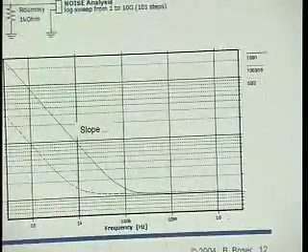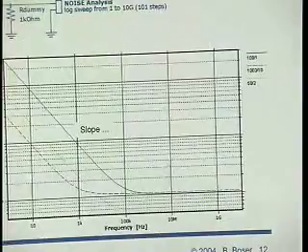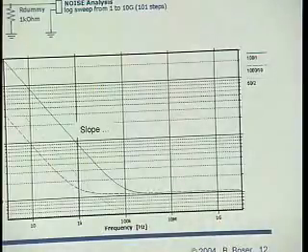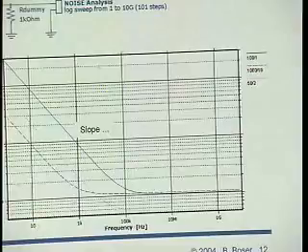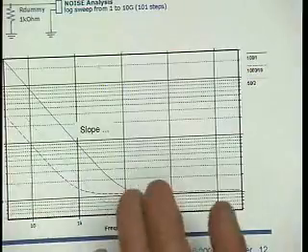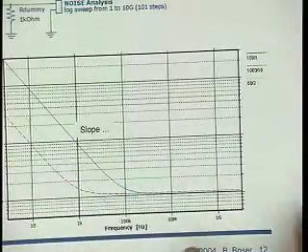The physical explanation for that is that flicker noise is a function of trapping: the larger a gate I have, the more I average out the effects of charge trapping, and consequently I get relatively much larger current, but less flicker noise.